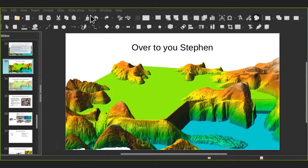So I'm going to talk a little bit about filling gaps in city elevation models, and we're going to go a little bit to a right angle from LiDAR and talk about photogrammetric data sets, which share characteristics, but also have some significant differences. Specifically, we're looking at photogrammetric data sets over Zanzibar and Tanzania. The Zanzibar Mapping Initiative is the largest area surveyed by low-cost drones in the world. It's fantastic, and I think it highlights some opportunities that we have. LiDAR is still the gold standard, but photogrammetric surveys allow us to do things that we might not be able to do with just LiDAR.